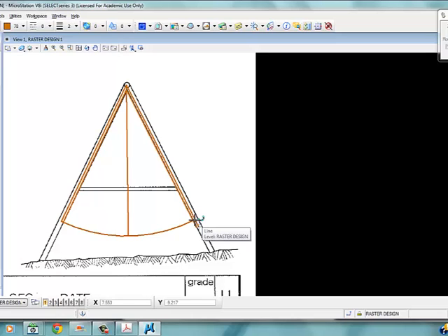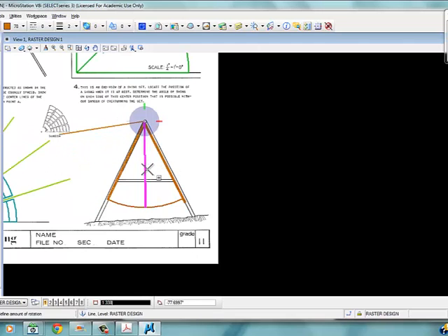So there's our angle. If we actually take our rotate tool now, 3-4, and we'll set it to 2 points, and we'll make copy. If I select this object, find this center point, then I can swing this angle up. Now I'm not sure where the point is where the swing set will overturn, but I can swing it in this direction this far, and then we can go back the other way however far you want, but we'll just do this one angle. So say if we get up this high, then the swing set may have a tendency to tip over, but I'm not into the physics enough. But we did find the bisector of the angle here pretty easily.